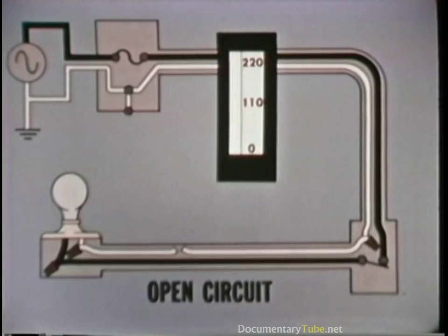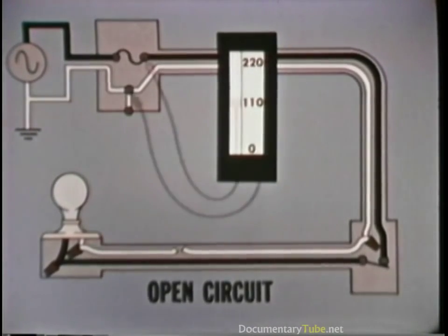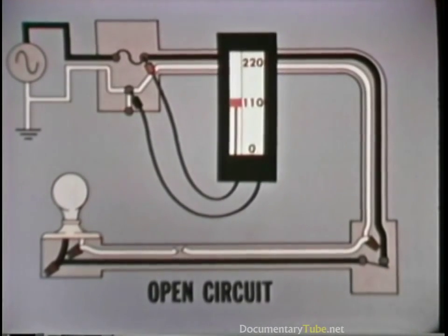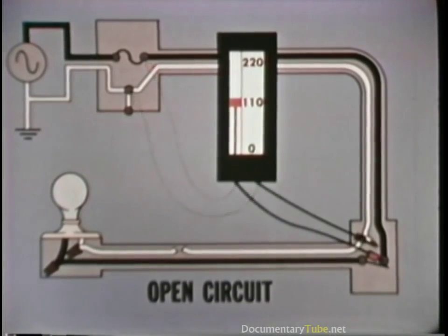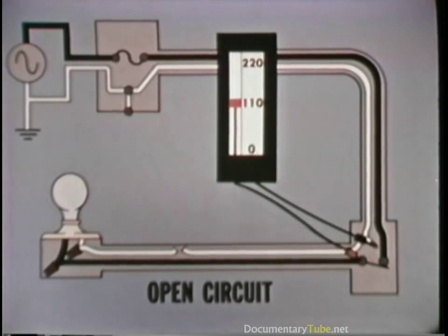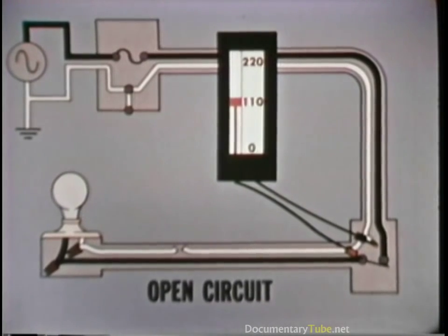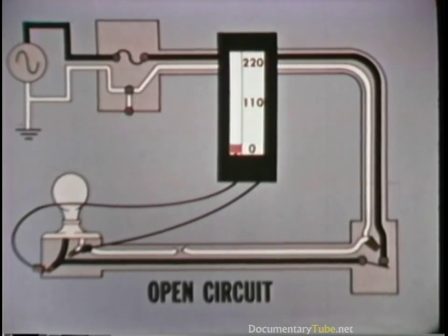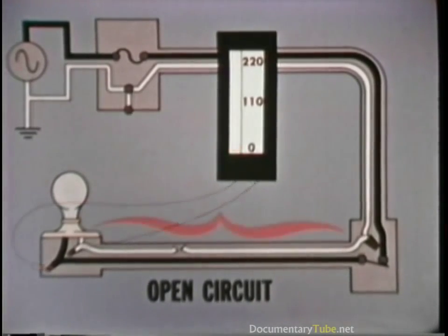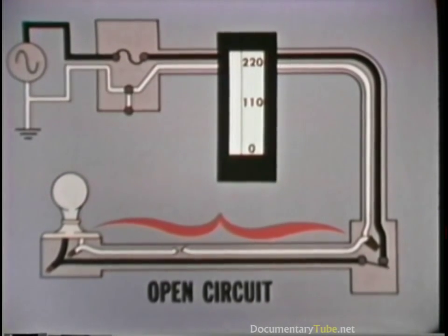The voltage tester will be valuable for this test. Checking at the source, there is voltage at the fuse box. Moving to the switch box, voltage is still present. Checking at the far side of the switch reveals voltage, so the switch is good. The final checkpoint is at the fixture box. At this point, there is no voltage. The trouble has been traced to this section of conduit.